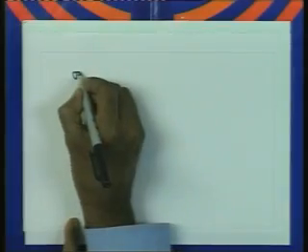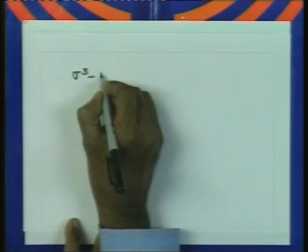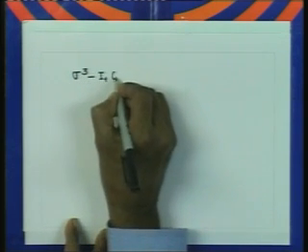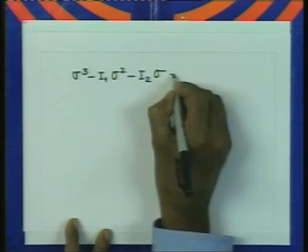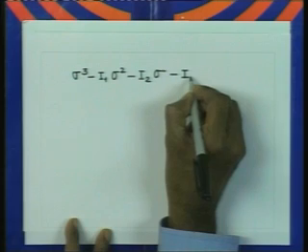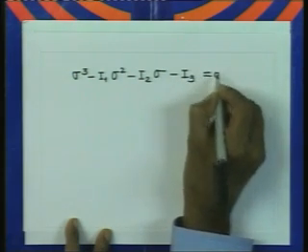Now, we would like to show that the principal stresses are real, they are not going to have complex quantity, since the equation that we had gotten by writing the characteristic equation was nothing but sigma cube minus I1 sigma square minus I2 sigma minus I3 equal to 0.